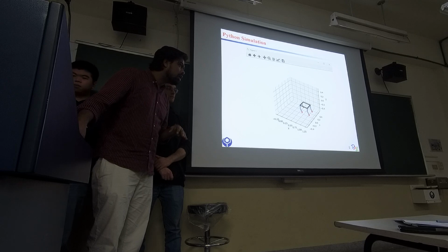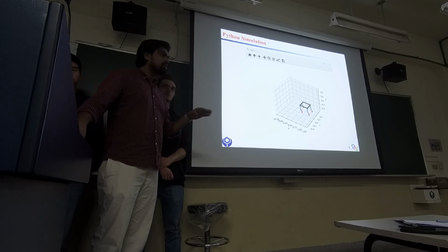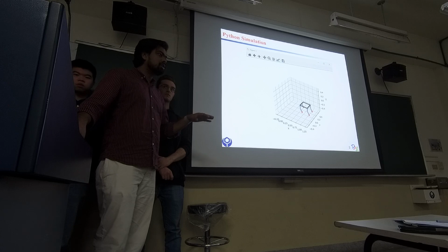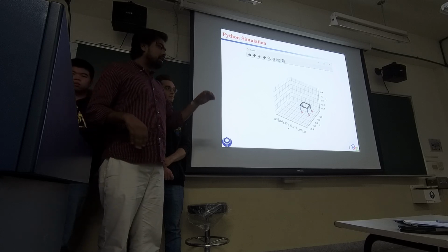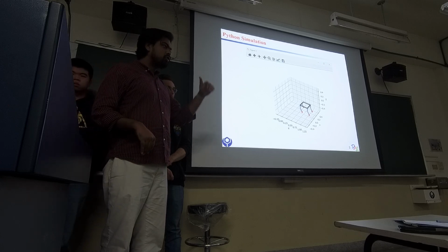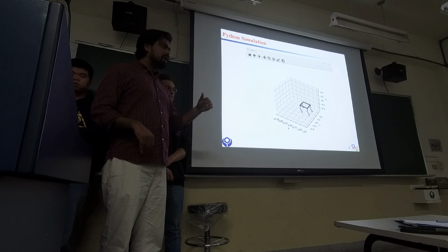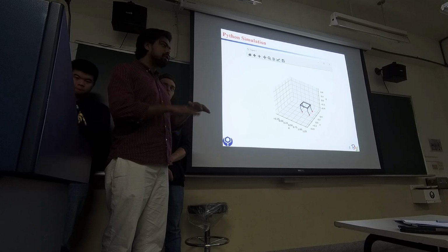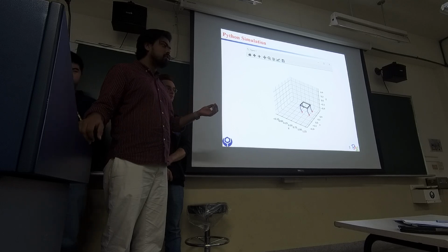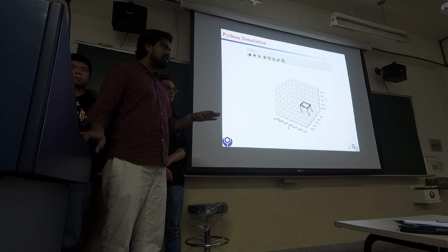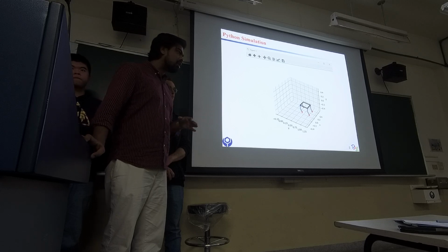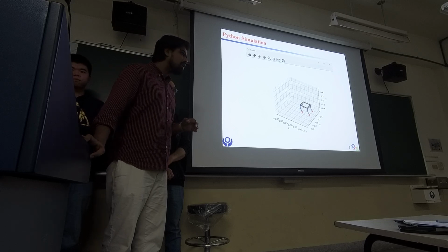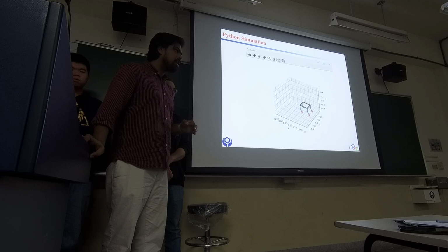How do you set up your force? You are not considering any applied force, but there is gravity acting downward, and on the four legs contacting the surface we have to take Coulomb friction, and that's it. So you have set up the friction on the wheels and also the gravity on the robot.